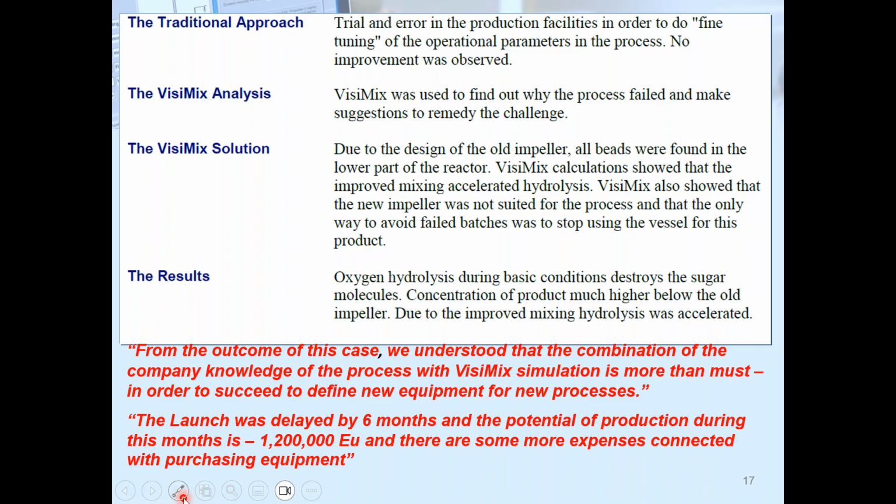And when we designed this new equipment, the quality was not so good. We detected that the reason was that the solid distribution was more homogeneous, but this homogeneity generated more interaction with the head space. The oxygen in the head space reacted with the part of the material in the top of the equipment and generated an impurity that was impossible to solve.